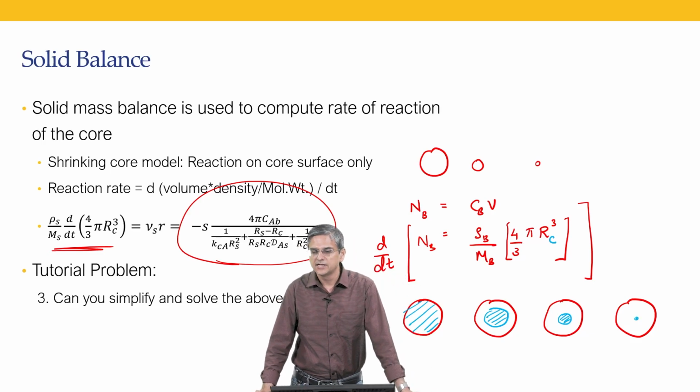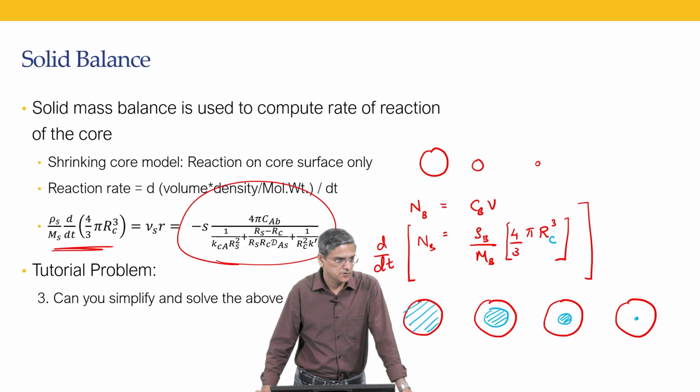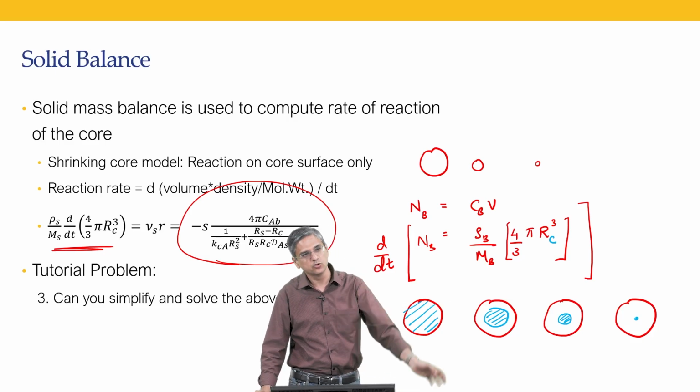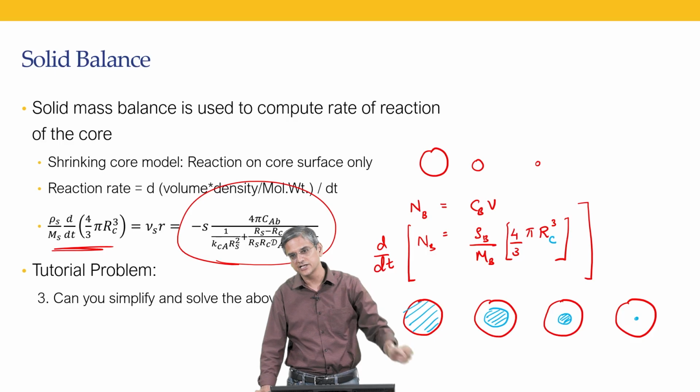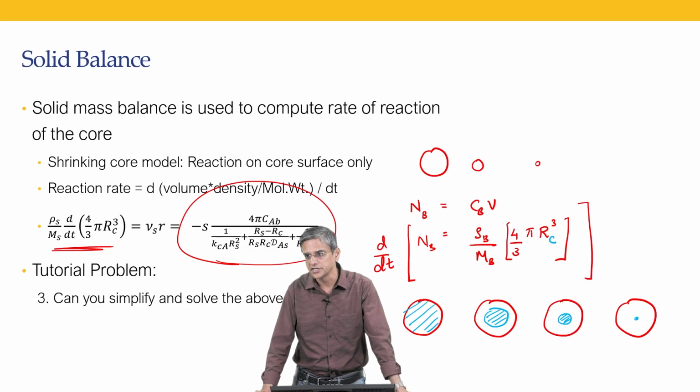Okay. Examples: if there is coke deposition in the particle, then you are decoking the particle. Example number 2 is let us say your coal, for example Indian coal has more than 40% of ash. As the coal burns, and if the ash does not get removed from the particle, the overall coal particle remains, the size remains the same, it is just that the reacting core keeps shrinking.